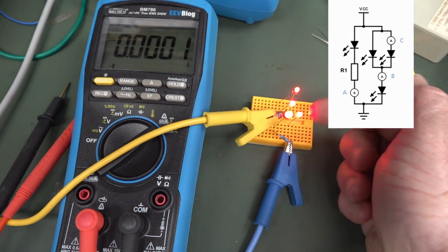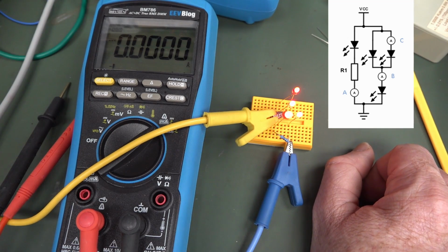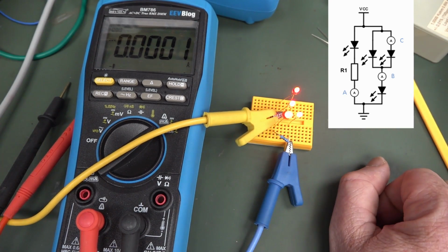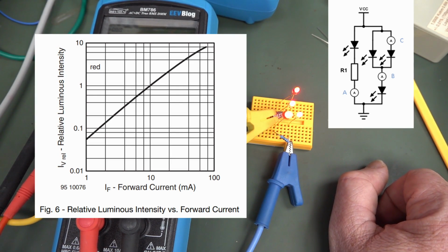If you had proper measurement instruments measuring the millicandelas or the lumens out of this thing, then you'd find that the brightness would be proportional to the current, because that's pretty linear. Having said that, diodes and LEDs are non-linear devices. They are in terms of voltage drop, but in terms of lumens output per milliamp through them, that's a pretty linear relationship for the most part.